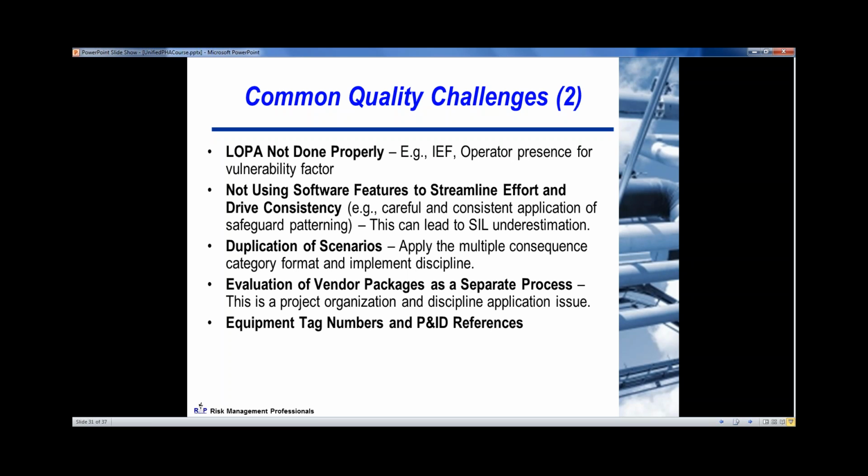That can help you agglomerate the challenges to the safety instrumented function to help you get a good safety integrity level. If you don't use that cross-referencing technique, and then you hand it to your instrumentation designer, they're going to look through the list, find the first entry, and go, okay, I only need a SIL 1, where maybe there are a lot more challenges to it.